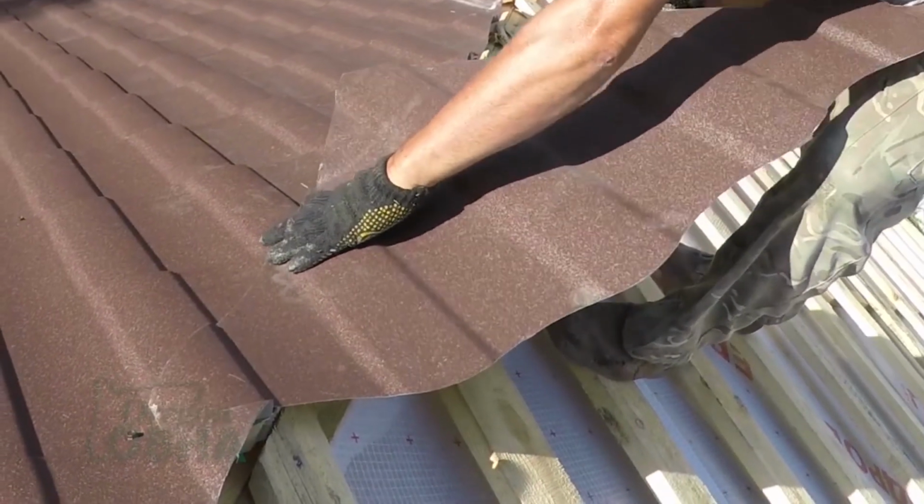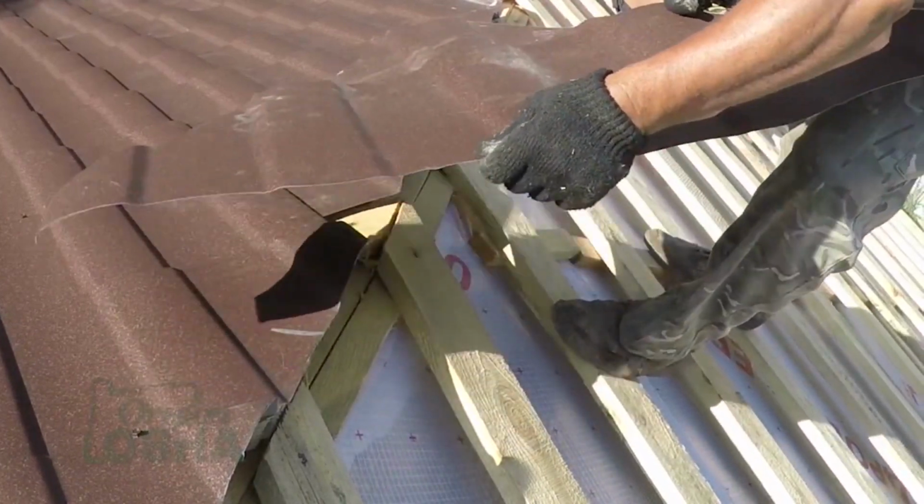Metal roofs are probably the most prone for accidents because of the sharp edges and having to cut and detail with those. And the slip hazard on metal roofs is a lot higher. When it comes to the slip hazards, it's really a hard thing to work with. You can't really do much. They do have some shoes that have a kind of felt pad on the bottom that help a little bit, but when it gets really dusty in the summertime, it makes it hard to work on. So really just planning your work so that you're not having to go back over things is key. Giving the employees gloves so that they can cut and work around the metal and minimize the chance of cutting their hands and fingers is a critical point too. And learning proper methods of cutting, because there are right and wrong ways to cut metal. If the employees learn the right way, that can help reduce a lot of risk as well.